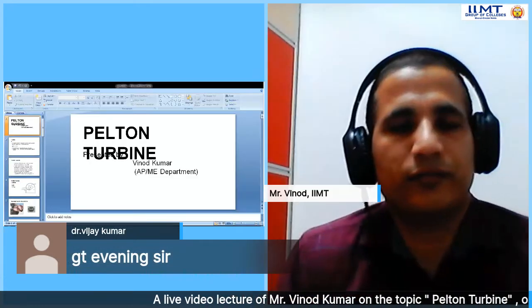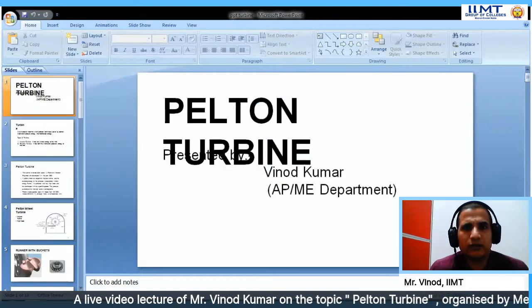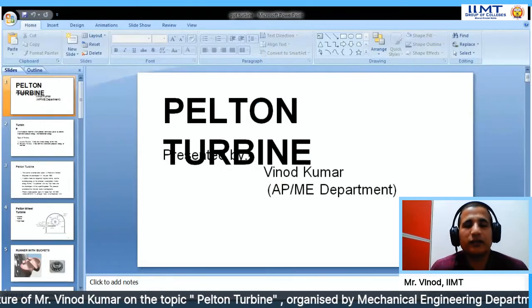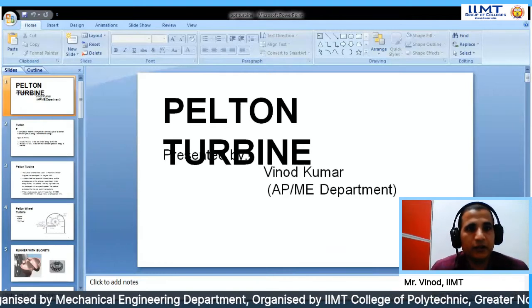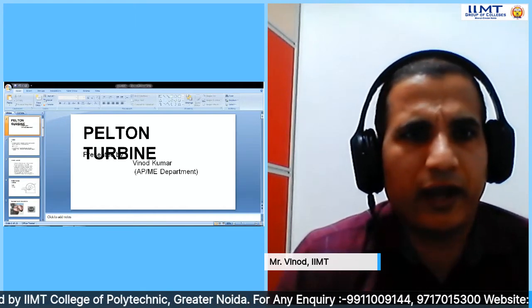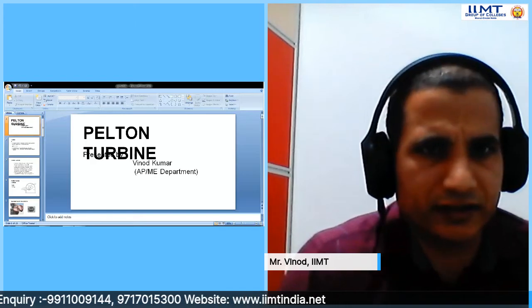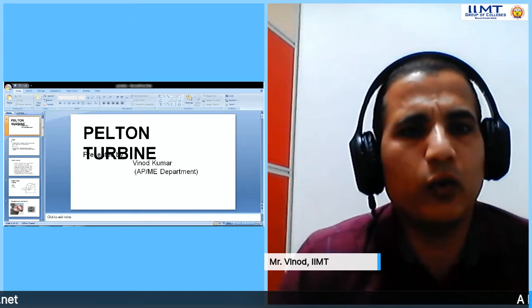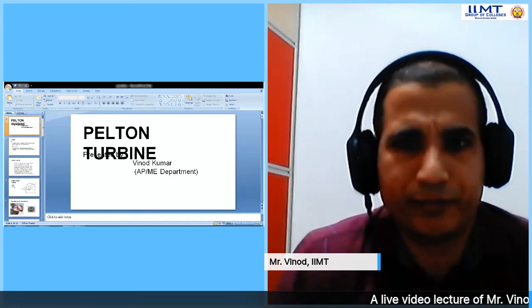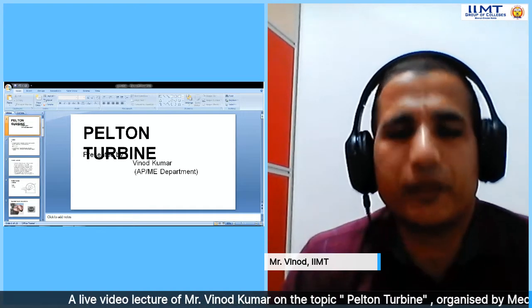Pelton turbine, let us discuss more about the Pelton turbine. This turbine is named after the scientist A. Pelton. This is an American engineer who developed it in the year 1880. Pelton wheel is a tangential impulse turbine, and the available energy at the entrance is completely kinetic. Further, it is preferred at a very high head and low discharges with low pressure. The pressure available at the inlet and outlet is atmospheric.